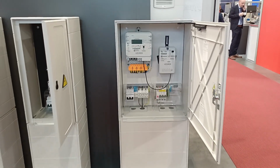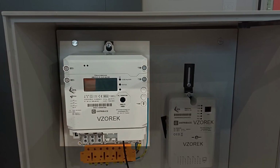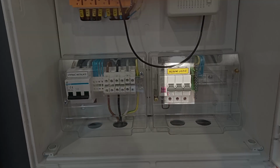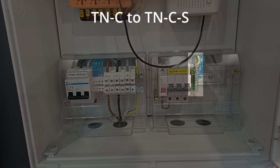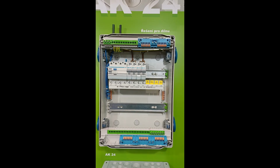Now we are at the level of a specific customer. This is the energy meter. And this is the main protection. This is the boundary between the grid and the user. This is where the system often transitions from TN-C to TN-C-S. That means the PEN conductor is split into PE and N. This is the final stage of the system.